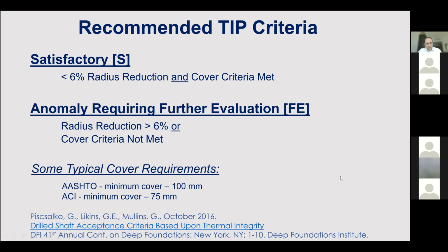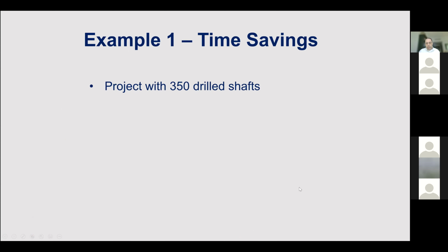Different foundations depend on the adopted project specification, the country codes, or the requirements from the employer. So you can have covers, say 75 millimeter as per ACI, or if AASHTO recommends, 100 millimeter of cover.